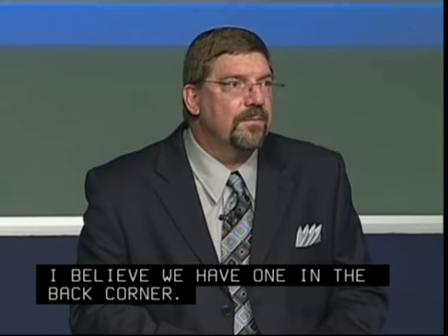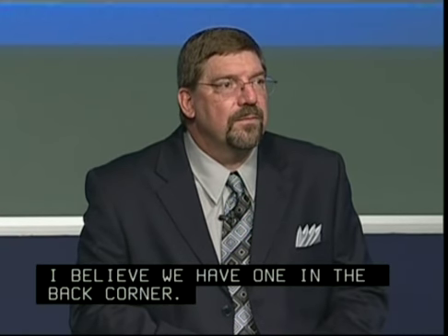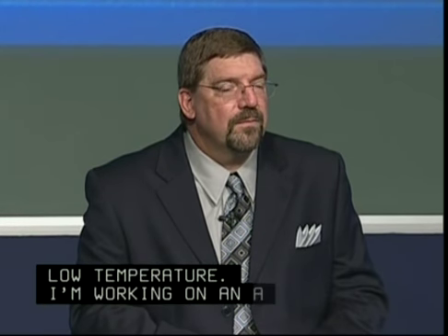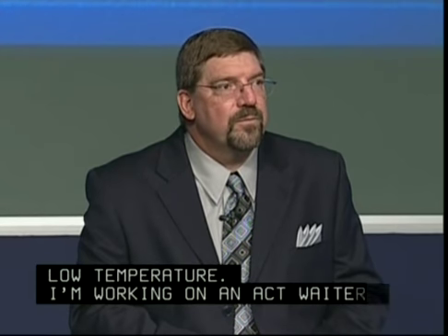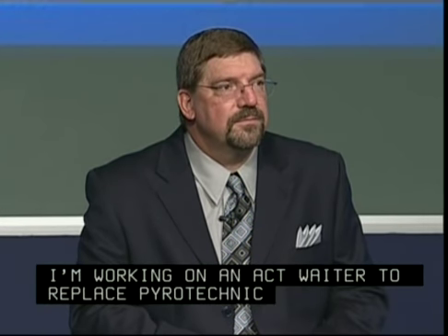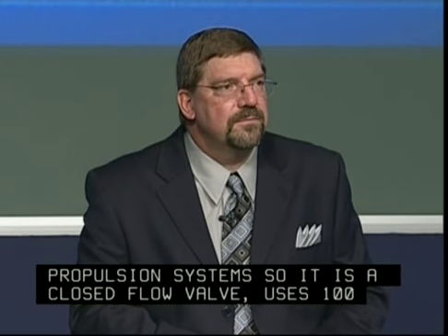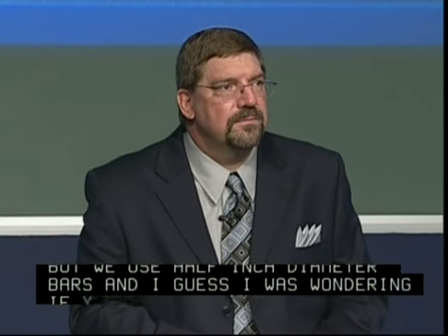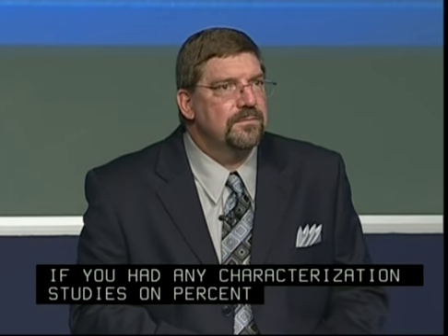Caitlin Eubank from NASA Goddard. I guess my application is more low temperature. I'm working on an actuator to replace pyrotechnic valves on propulsion systems. So it's a normally closed flow valve. It uses about 100 C actuation. But we use half-inch diameter bars. And I was wondering if you had any characterization studies on percent recovery and force produced from bars versus wires in the low temperature regime.